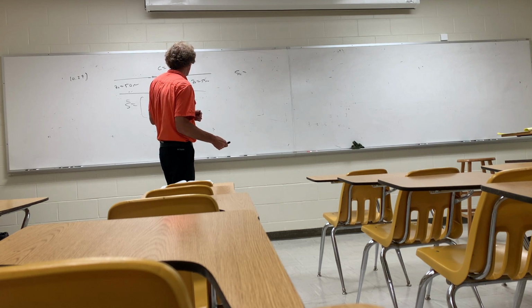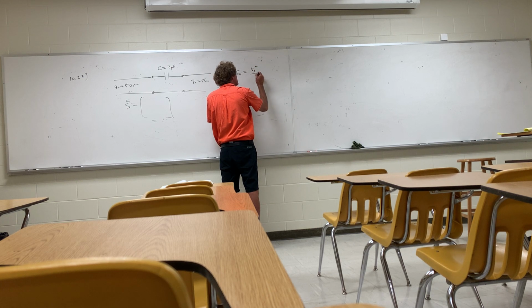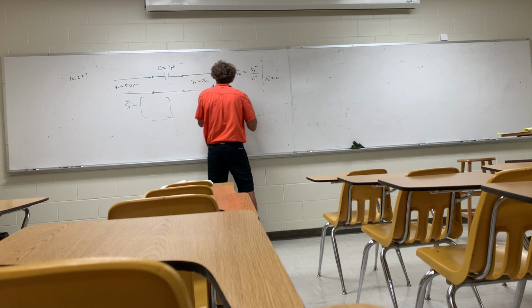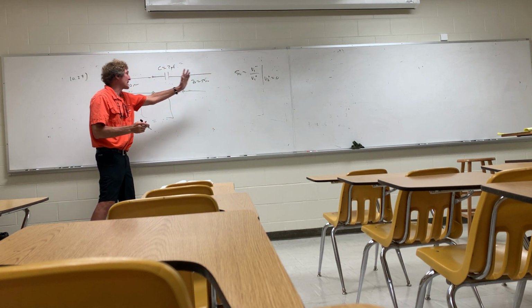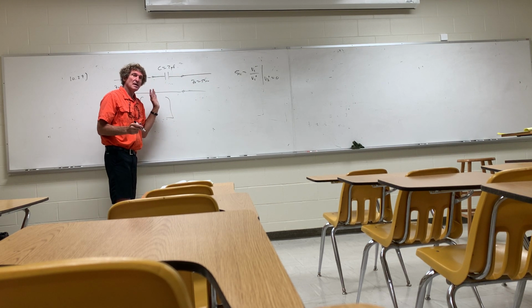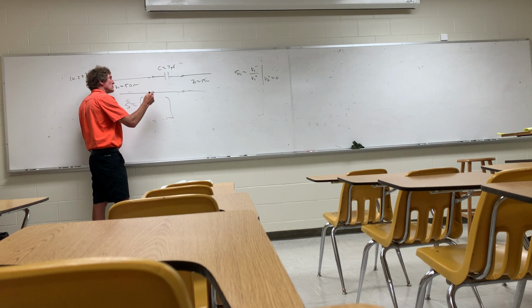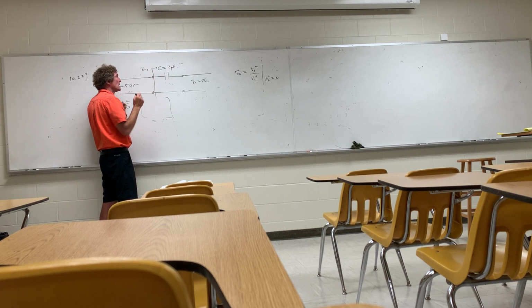So how do we get S11? What is it by definition? It's V1 minus over V1 plus, assuming V2 plus is 0. So really just think that this is matched. I'm not going to keep redrawing. There's nothing coming back at you; anything that gets through here is not going to reflect back. So what would that be? Where do you start? What's the one thing I need for all these? I need Z in right there for port 1, don't I?